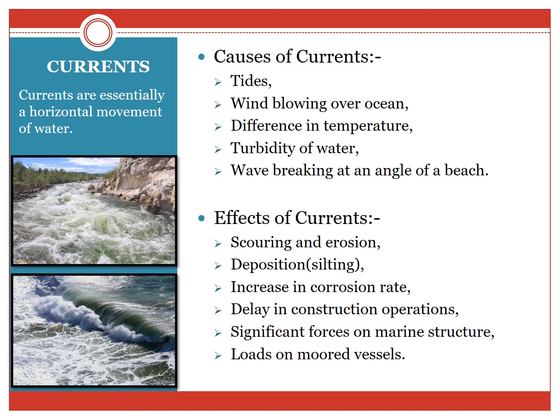Because of the current, the vessels or the ships have a horizontal movement to each other. It is desirable that to a large extent harbors are free from both erosion and silting. Erosion may undermine the foundation of the structures and silting will result in reducing the depth of water in the approach channel and the turning basin, which also impacts the ships.